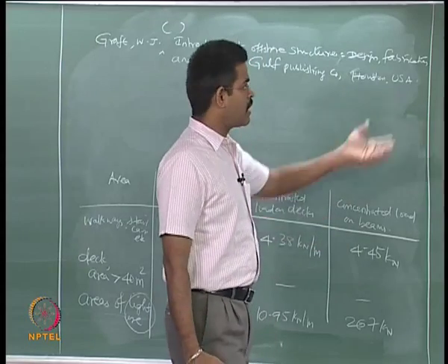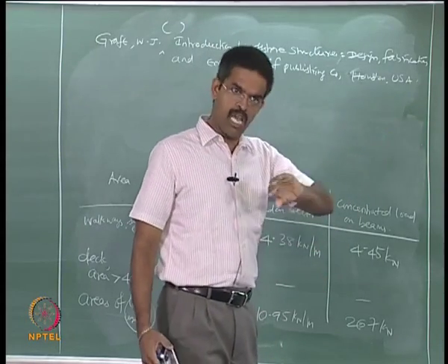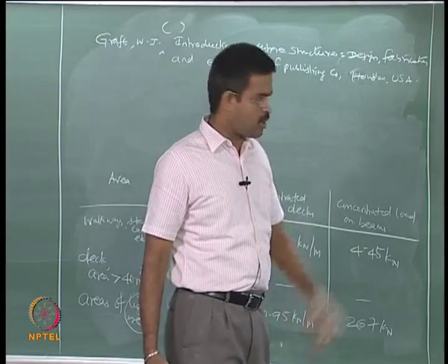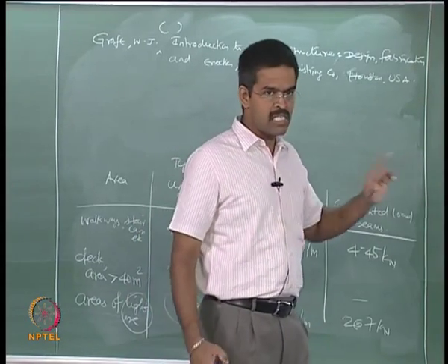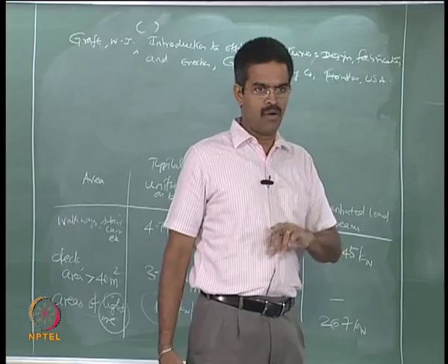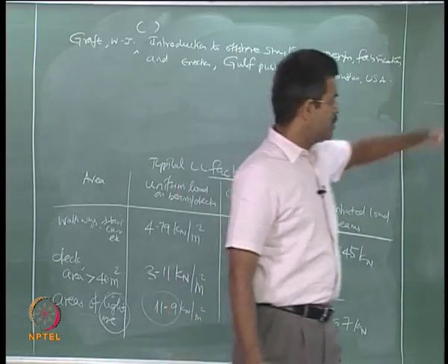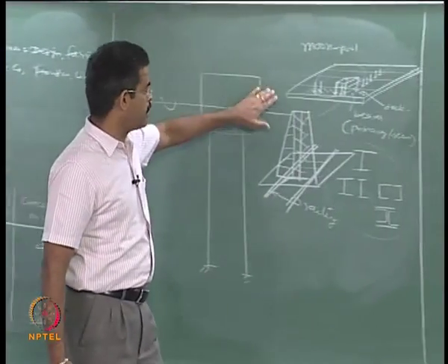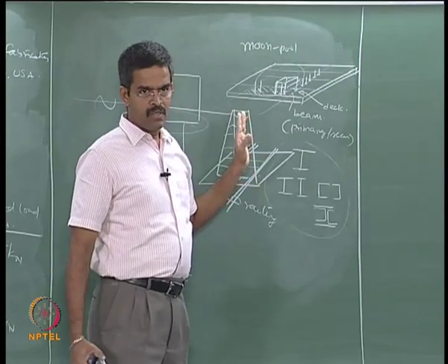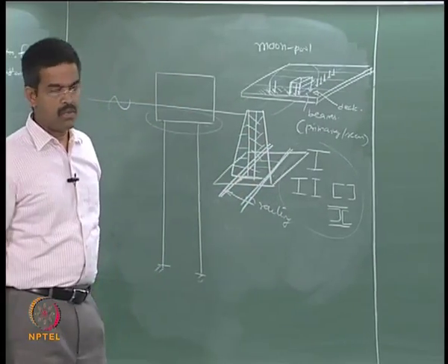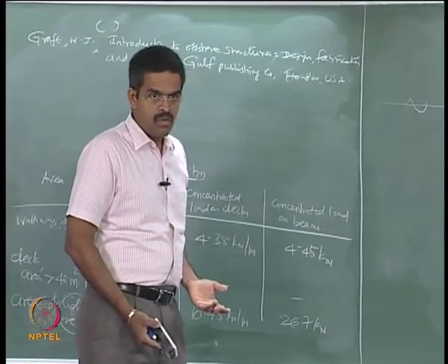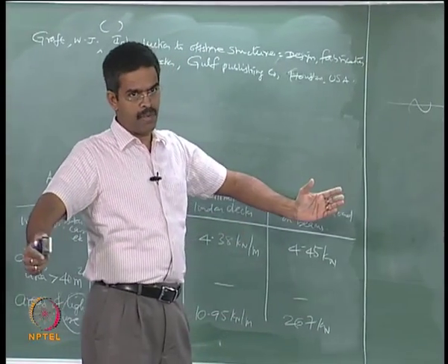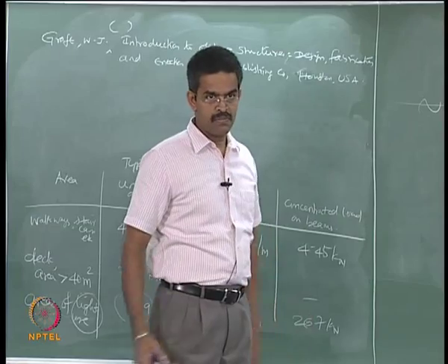Similarly here, when an equipment is operating and you want to change the operational speed because of requirements from the operational mechanism, those changes will all affect, or get affected by, the boundary on which it is restrained, nothing but the platform deck. So they all will be impact loads. Now the question is, it is very difficult to find out what this impact load would be on an average operation of an equipment on a floating system like this.